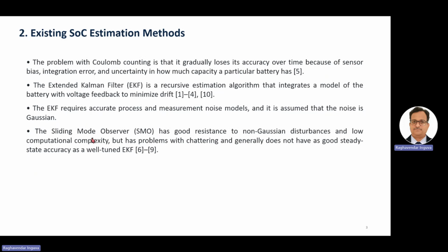Next, one more method is the sliding mode observer. We'll be calling it SMO from hereafter. It has very good resistance to non-Gaussian disturbances. Unlike EKF, it can handle non-Gaussian disturbances. It has very low computational complexity, and the mathematical formulation is very simple. But the problem with SMO is that it is prone to chattering.